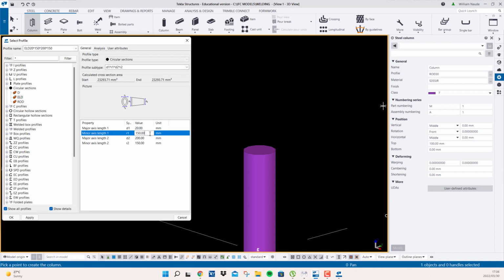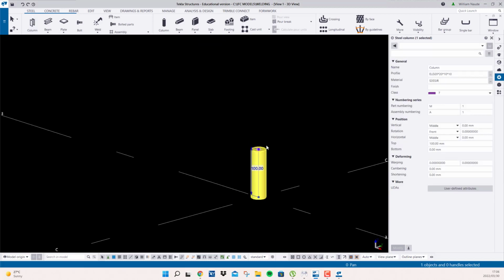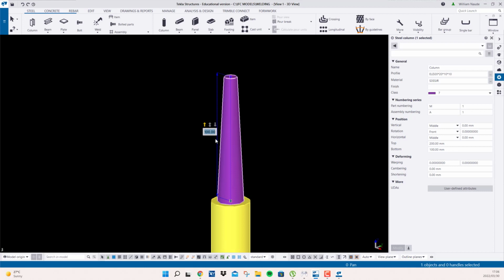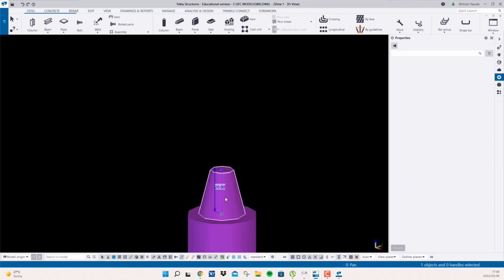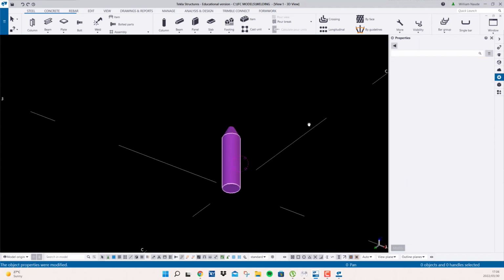So this is a very long method. What I'm going to do is work rather with what we have right here. So I'm going to go with also 20, and we're going to make this 10 by 10, and we're going to apply this and place it right over here and say keep the duplicates. And I'm going to move this one up all the way here, and we're going to shorten it by saying this should be, let's say 20 long. Right, so now we have a 20, but the rod is 30, I forgot, so I'm currently in the wrong. So we have to say 30 by 30, and we keep it at 10. So now we have what's called a sharp point.